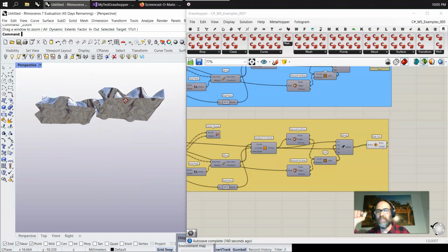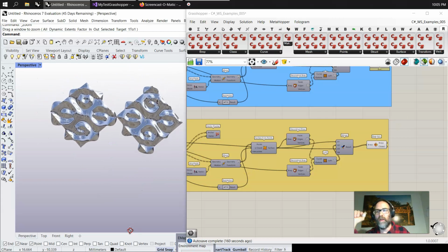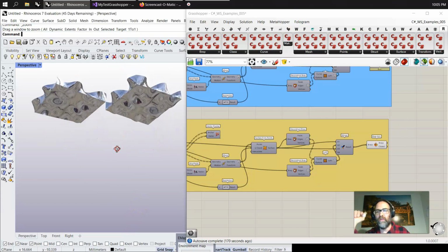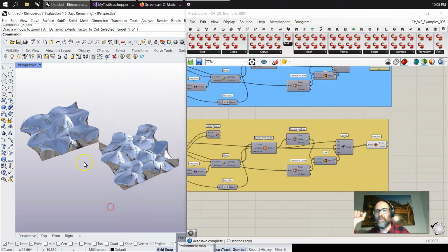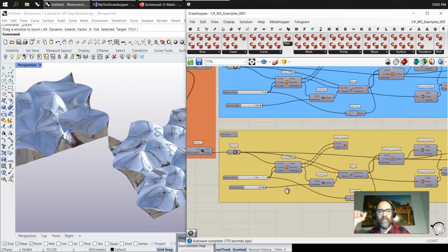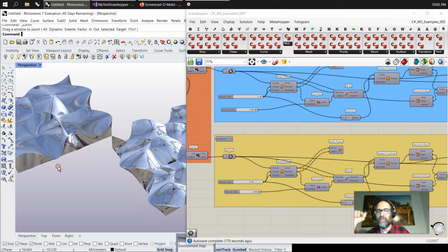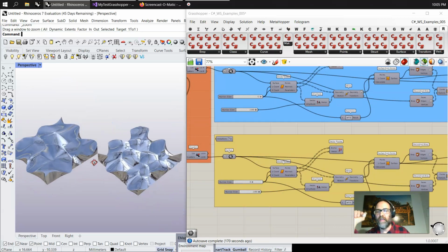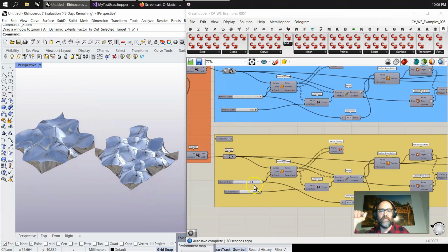What's nice is this does not have to match up. It matches up on each one. There's symmetry on the bottoms. But because of the different thicknesses that I'm playing with in here, I actually set them both to 2, they're going to have, because of different number counts, different surface edits as I go through here. If I take a look at that one, you'll see an effect of changing the surface really nicely from no count to a full count. You can match that, or you can let it step off of itself. So I think I'll leave it at 8 and let it match it.